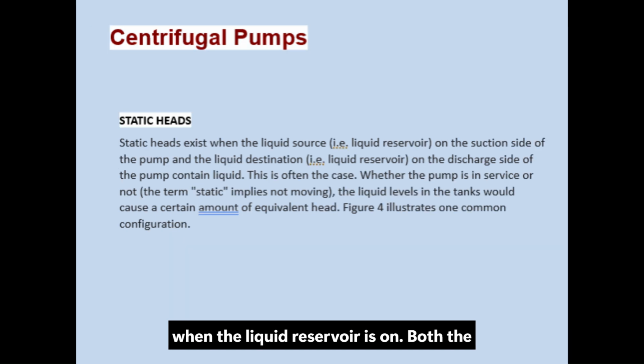Static heads exist when the liquid reservoirs on both the suction and discharge sides of the pump contain liquid. Whether the pump is running or not, the liquid levels in these tanks create a certain equivalent head. The term static implies a non-moving condition. Figure 4 illustrates one common pump configuration showing these static head relationships.